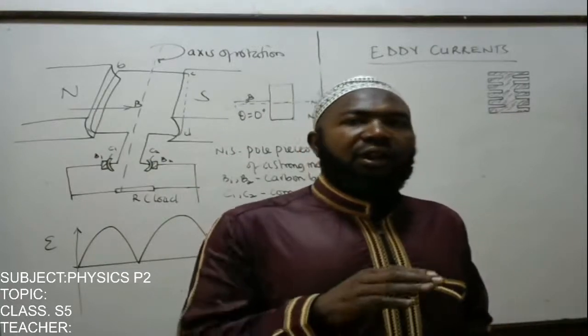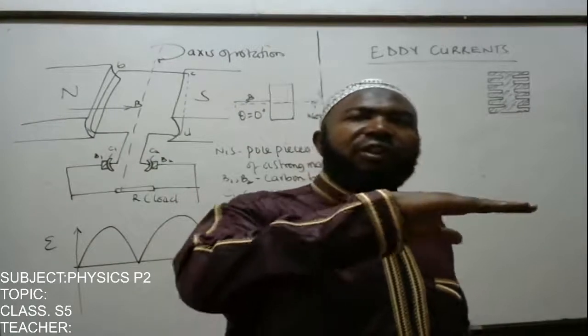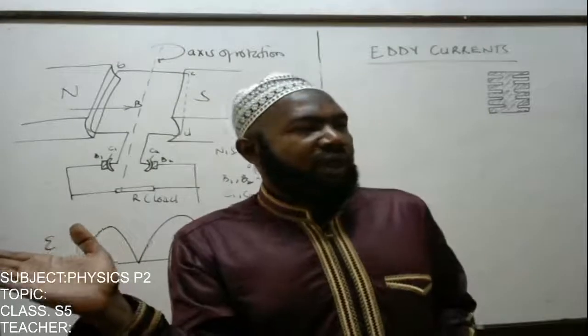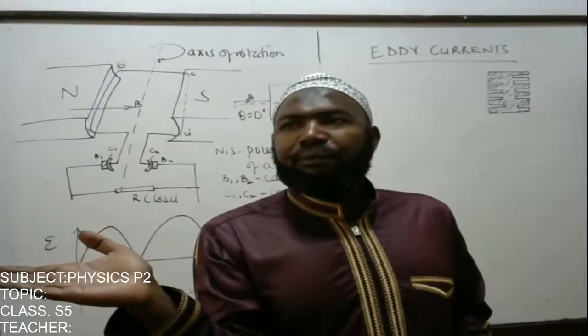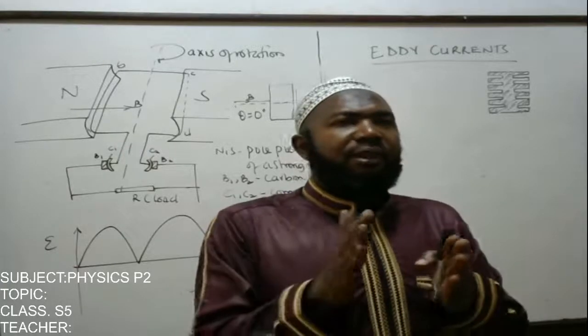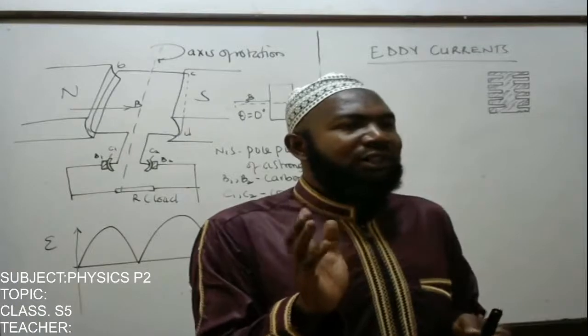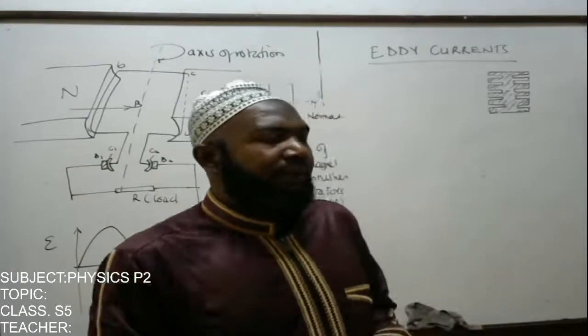In other words, the current that is urging the torque within the coil is moving in one direction, and the eddy currents are forcing the pointer to move in the reverse direction. So at equilibrium, the pointer settles in one position without oscillating many times per second.